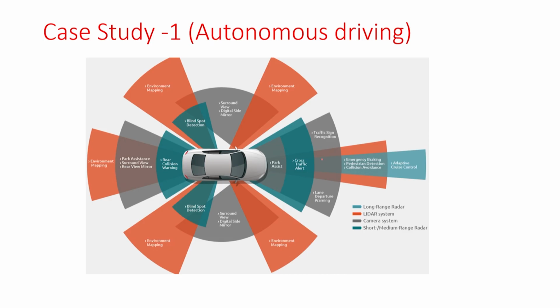So, in this example we will see what kinds of sensing systems there are within, suppose, your vehicle. I have already chalked it out. You have your radar, obviously a very important function, long range radar. What is the range of this radar? Maximum 250 to 300 meters, not more than that. If it is a short range radar, it will be 120 to 150 meters, mostly 120 meters. Beyond 120 meters you won't get detections with good RCS or good signal to noise ratio.